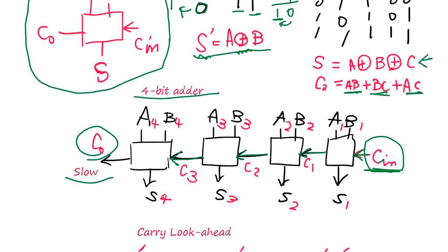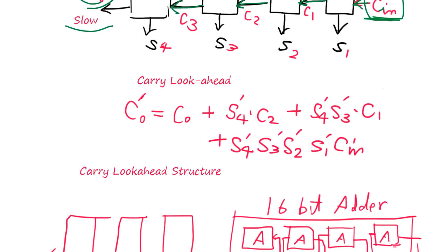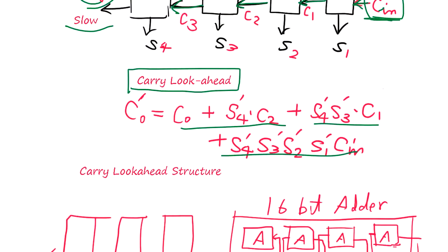So the very standard way to deal with this is to use a carry-lookahead. For the 4-bit numbers, you make a separate circuit to figure out the carry out. So this circuit is going to figure out the carry out, and it doesn't have to go through many gates.